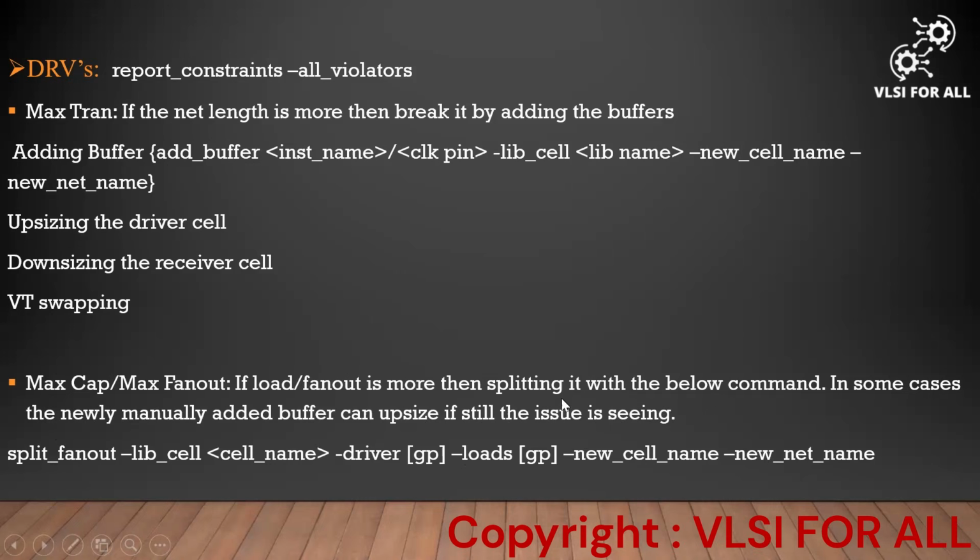I have faced such issues, so I have added this here for better understanding. In some cases, after giving this command, we won't see the cap or fan out issue fixed. Then we can upsize the driver cell which we added manually, and then the max cap issue gets resolved.